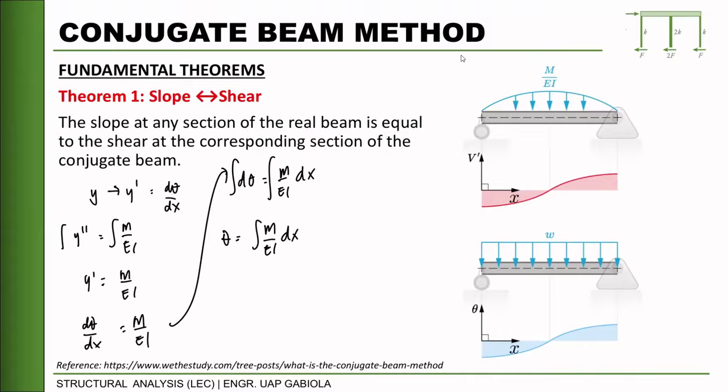Then, from our shear and moment equations before, if you would like to check if our shear equation is correct, we take the derivative of the shear with respect to x and check if it is equal to the applied loading. When we perform this, dV equals the loading times dx; integrating it, we have V equals the integral of w dx.